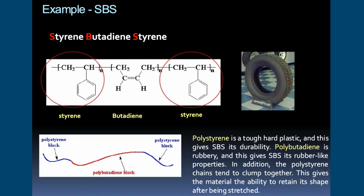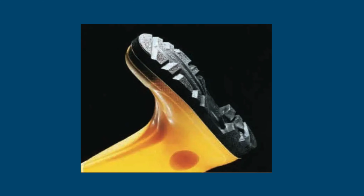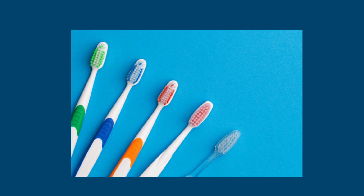Another technologically important class comprises triblock copolymers, such as styrene-butadiene-styrene, SBS, and its hydrogenated analog styrene-ethylene/butylene-styrene, SEBS. These materials behave as thermoplastic elastomers because glassy polystyrene domains function as reversible physical crosslinks dispersed within a soft rubbery matrix. Unlike conventional vulcanized rubber, SBS and SEBS can be repeatedly melted and reprocessed, making them attractive for footwear, medical tubing, pressure-sensitive adhesives, asphalt modification, and flexible consumer products.